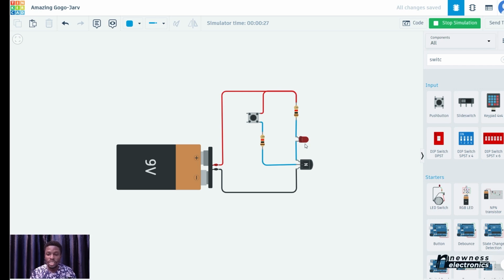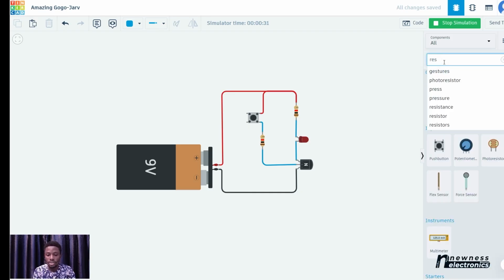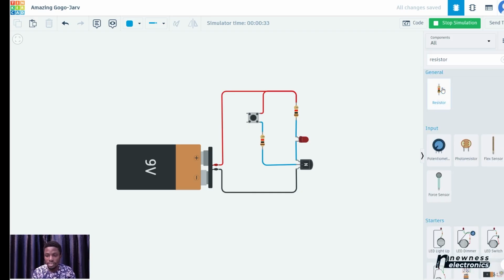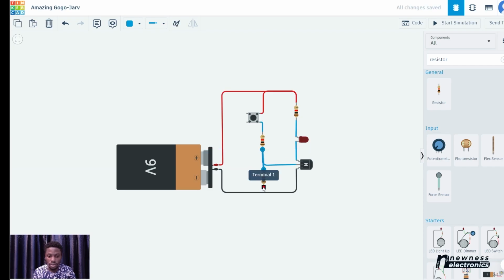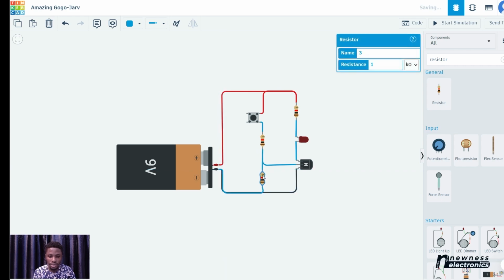which is sufficient for it to turn on. So to prevent that, we need to add another resistor to the base of the transistor. What does this resistor do? It creates a pathway to ground or to negative, so that any tiny current, when the transistor is not conducting, can be dealt with.